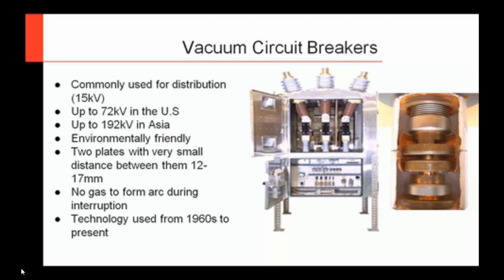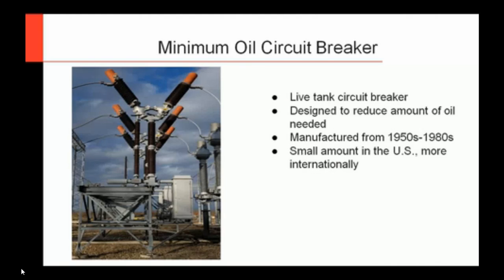I've seen maybe like an SF6 circuit breaker that they're using at like 32 kV or something, but it's usually like a 72 kV design. They went down because they needed higher fault interruption current.